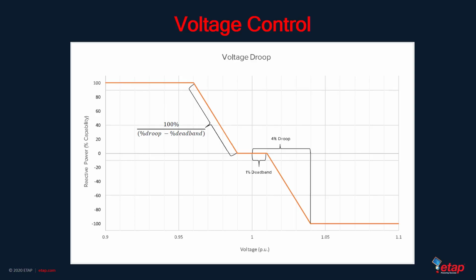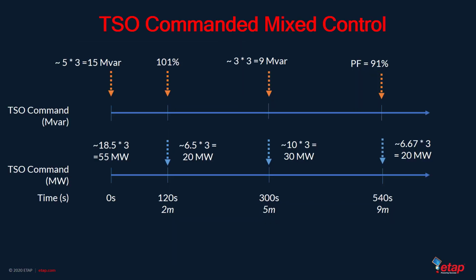Now that we've looked at an example for voltage control, let's have a quick discussion and a demonstration of active power control. So active power control is one of the two system directives. The primary objective of active power control obviously is to control the real power production at the point of interconnection. Therefore, the balancing authorities or the off-takers and the power purchase agreement will basically decide how much power a plant is required to produce at any given point in time. The plant is obligated to track that set point and produce the commanded power when possible.